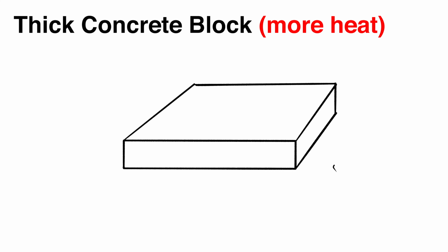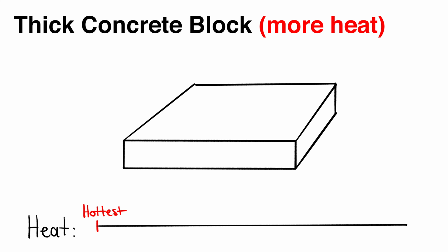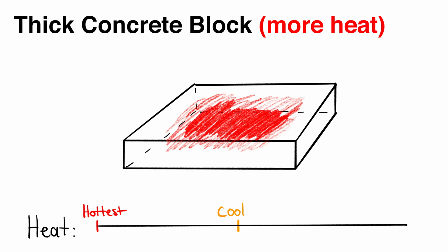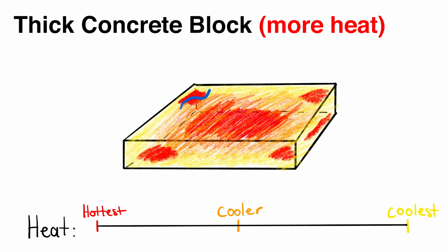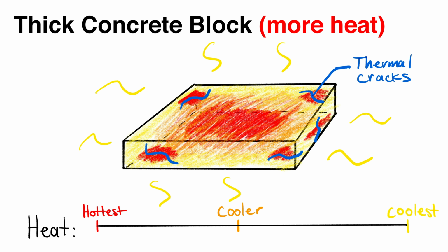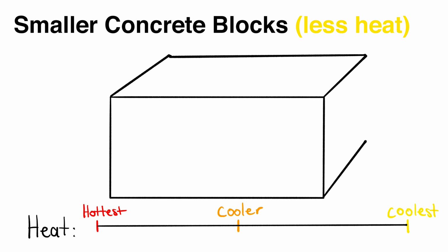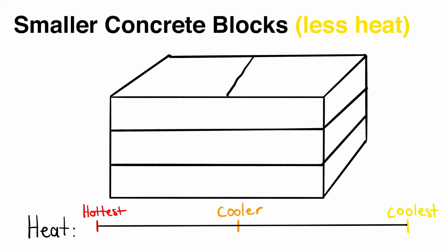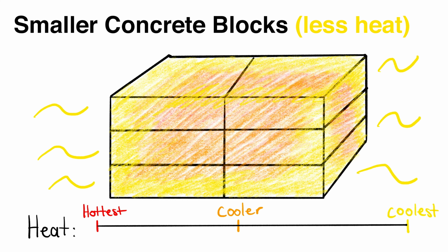In thick casts of concrete, there are natural temperature differentials between the inside and outside as it cures. The problem is that some of the areas of concrete will be expanding rapidly while others not so much. This ultimately causes tensile stress that will lead to thermal cracks if the tensile resistance of the concrete is exceeded. Essentially, to avoid thermal cracking, the Hoover Dam was casted in smaller blocks instead of one large wall. However, this alone wasn't enough.